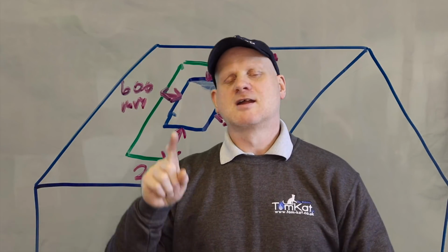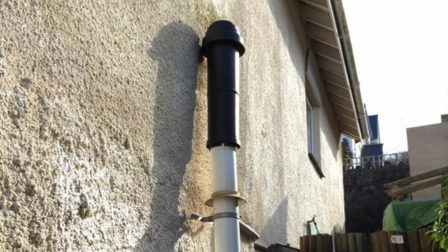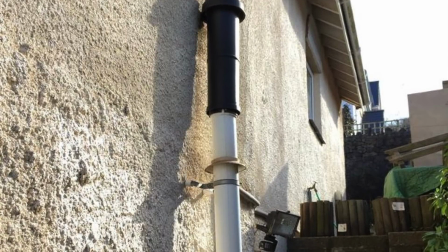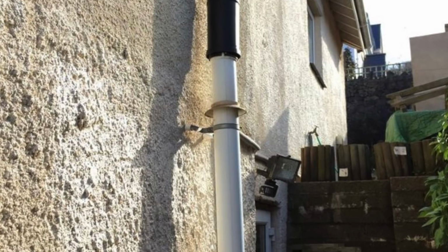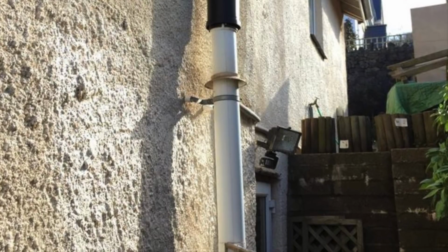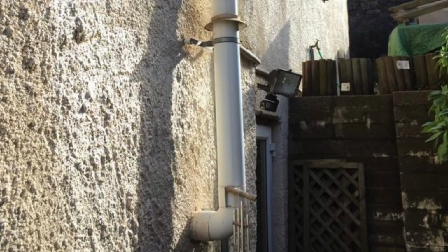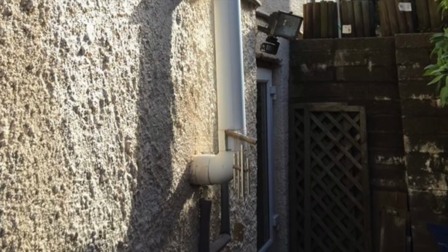flues and voids, I just want to show you this last picture. Can somebody tell me why this vertical flue has been installed in this position? Now this vertical flue should be at least 500mm away from a wall which is non-combustible, or 1 meter away from a wall which is combustible. I just don't get why this flue has been installed like this. Why did they not use a Plume Management Kit?